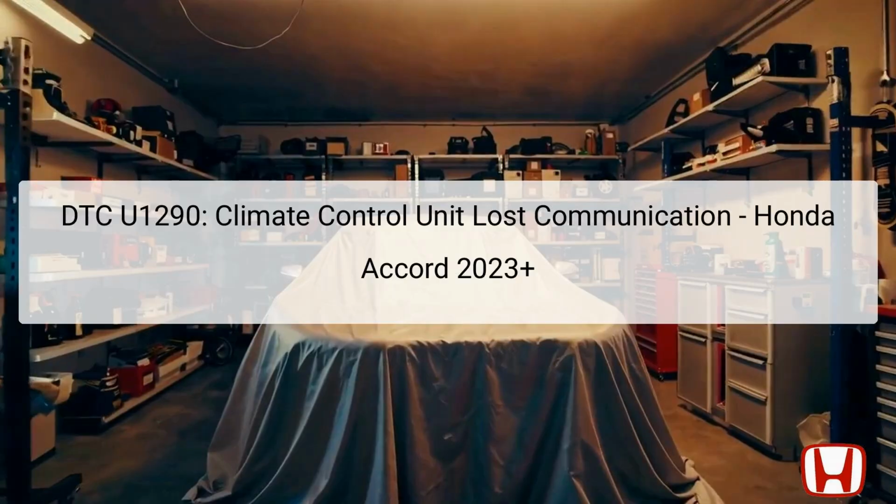The DTC U1290, associated with the climate control unit, indicates a loss of communication with the front seat heater control unit in the Honda Accord 2023 and beyond. When the climate control unit fails to receive the required data from the front seat heater control unit, it determines that an anomaly exists, leading to the storage of this diagnostic trouble code, DTC.